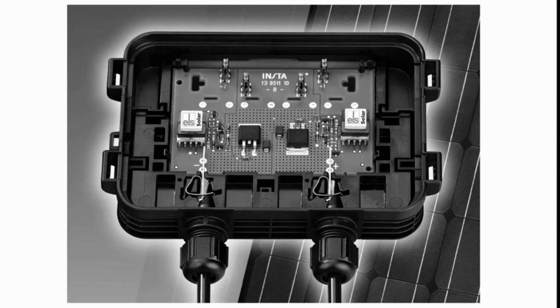This is a more modern approach for the bypass diodes, because you want to avoid the losses. So this is an electronic device that detects shading and then carries out the bypass process without the losses of the bypass diodes. Unfortunately, this was too expensive, so it wasn't applied by the module manufacturers a lot. Cost was about, I think, 20 euros or something like this, while nowadays a module costs only 100 to 150 euros. So this was quite a considerable cost. And if you compare it to a bypass diode, which costs maybe 50 or 40 cents, this was unbearable.